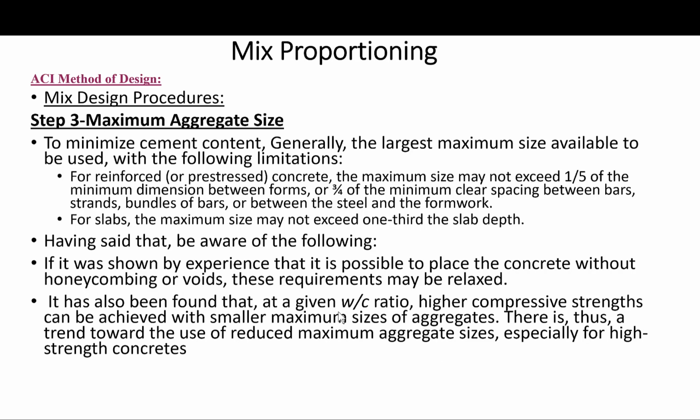Step number 3, the maximum aggregate size. Generally, the largest maximum size of aggregate available, consistent with the limitations to be listed here, should be used, as this will minimize the required cement content. If you remember, we talked about the maximum aggregate size. The limitations on the maximum aggregate size are as follows.